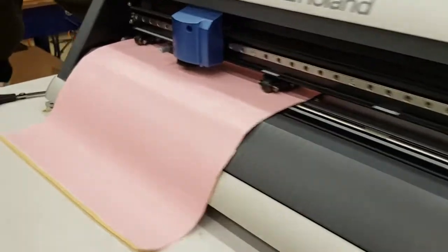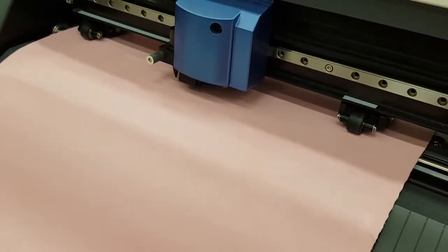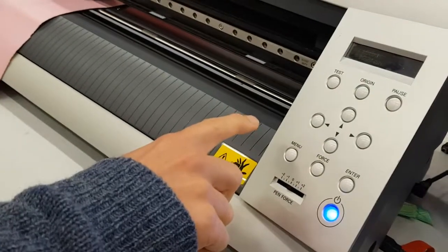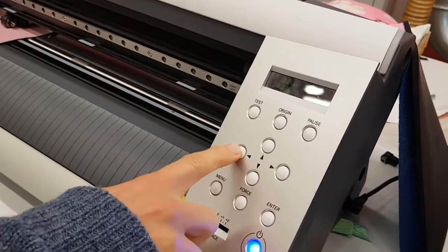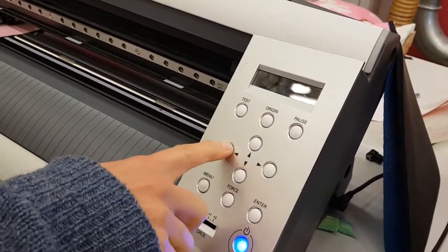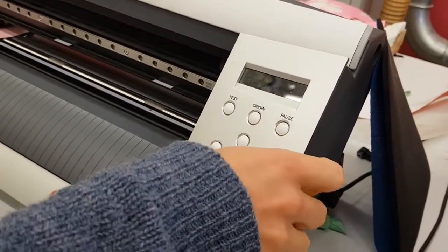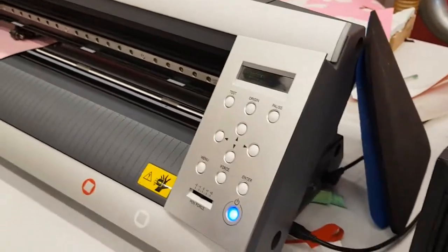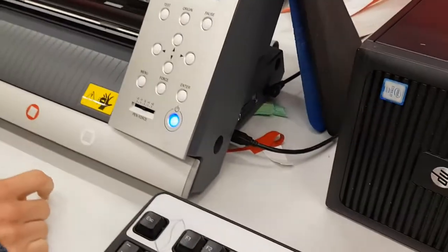If we jog the head around and put the origin in a different point, then it will start from that point. Okay, so maybe we can move the origin over here. So your design is 160 wide, and the material is only 150 wide. So the design was going to crop off the edge anyway. Oh wait, no. The material's 260 wide. So the furthest across we could be would be over here somewhere. And then obviously you can be as much front and back as you want. How far from the back do you want to be? Just so they don't overlap. Okay, so you want to start from here.